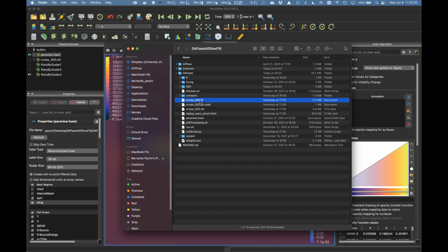So if you look at the TACS documentation, which I can post a link to after this in the chat, or some instructions elsewhere on the DAFoam website, you just simply run that utility, and it's called f5tovtk, which goes to ParaView like we're using, or f5totec, which goes to Tecplot, which is this .plt file here. So I can't show it because I don't have that running on this computer, but it's just a one-line command that will convert all of your f5 files, if there are multiple, into visualization files that you can use for Tecplot or ParaView.